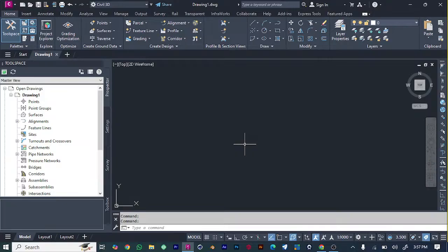The first thing that you need to know is that in Civil 3D, when you want to draw a road, you will collaborate with the surveyor. The surveyor will give you the survey data which you will use to create your alignment, corridors and other stuff. So you need to be very keen on that data. If he gets it wrong, you might also get it wrong. Remember that AutoCAD Civil 3D is software that, when you command it right, will give you correct things. But when you do messy, it will give you messy stuff.